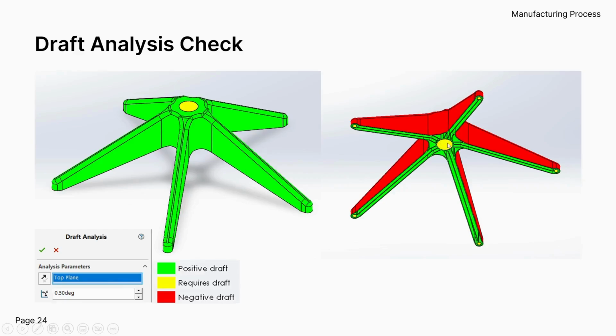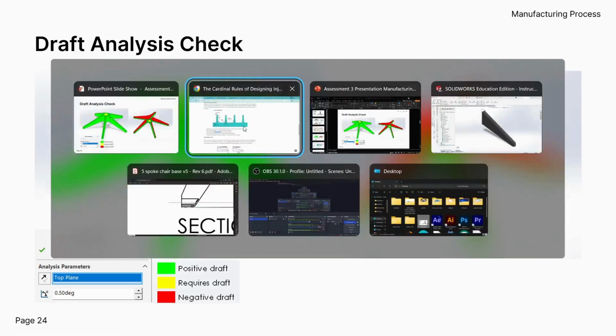The reason these are all yellow is because of requirements and specifications by our lecturer, as these are all caster wheels and hydraulic pistons, which already have a certain diameter, and they do not want them to be angled at all. Other than special circumstances like this, all of your injection molded parts should be angled towards the A and B part so that they can be ejected out easily.